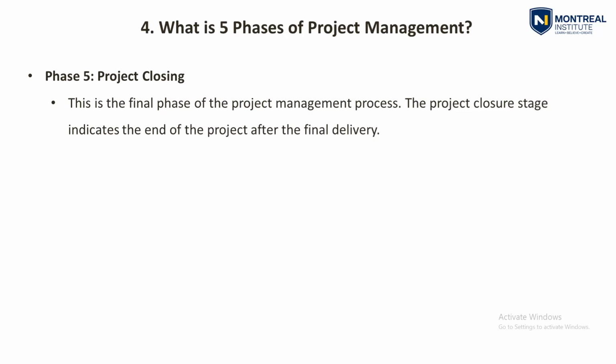It can start before the completion of the project, because the documentation will take 2-3 months. So before completing your physical works, you can start the documentation 2-3 months ahead. At the end of the project, you will have all the documents to be submitted, as-builts, manuals and spare parts ready, and you will come out of the project after getting the final completion certificate. Maybe you will get the partial completion certificate first, and after the maintenance period, you will get the full completion certificate for the project.